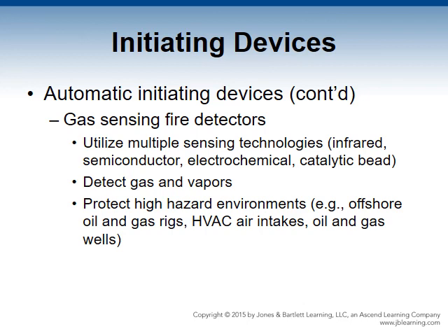Gas sensing fire detectors. They utilize multiple sensing technologies, such as infrared, semiconductors, electrochemical, and catalytic bead. They detect gas and vapors associated with a process that uses hydrocarbons. They protect high hazard environments like offshore oil and gas rigs and HVAC air intakes.